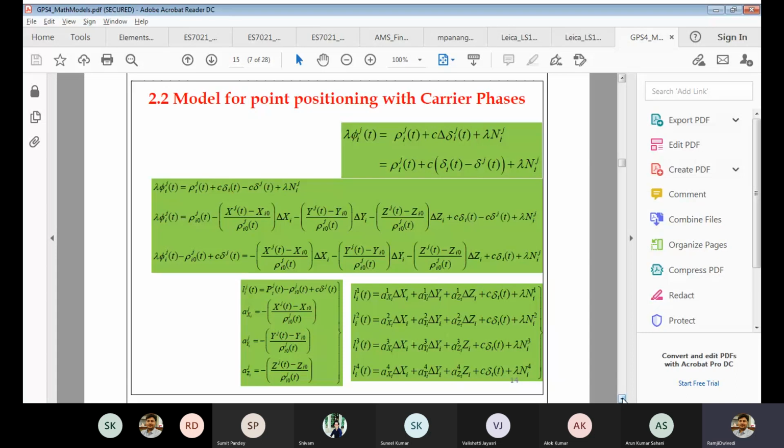No, it is because the satellite informs you about its clock error with the help of the navigation message. You can get the parameters by which you know how much drift is there in that clock. That's why it has become observable on the left hand side. But the receiver clock error is a very poor standard clock. The offset in the receiver clock is never known to you. You have to estimate the error. Okay, sir. Got it.